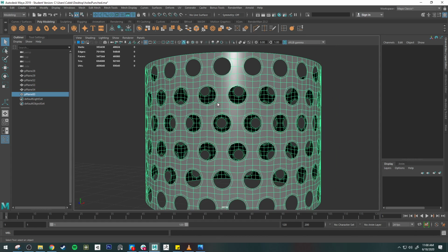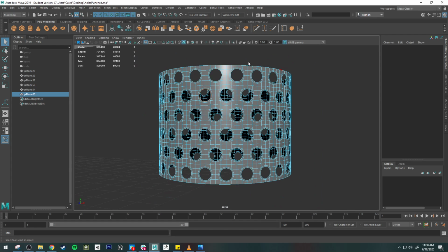Right, is I could extrude or push back these holes. The problem is, oh no, I've already done this entire object. What the heck am I supposed to do now? I'm going to have to Control Z back, push it back, and then reduplicate it and do the duplicate special and wrap it so that all of these holes have the exact same transformation. Or I have to select all of these guys, which is a pain in the butt, and move them back or scale them back, right?